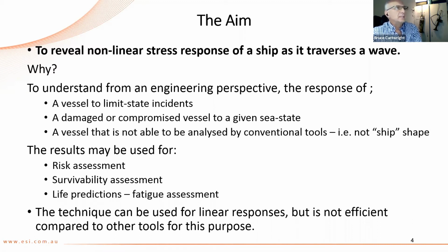Or really a vessel that is not able to be analysed by conventional tools. So it might not be a conventional ship shape, and it might not conform to the usual rules of thumb or the empirical formula. Again, whatever you want to use the results for: risk assessment, survivability assessment, life predictions, fatigue assessment. And the real key here is that we're looking at non-linear responses.